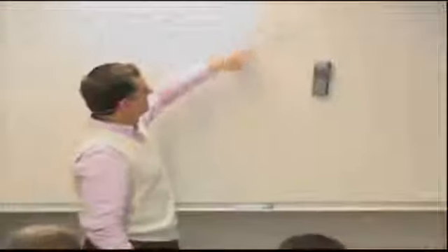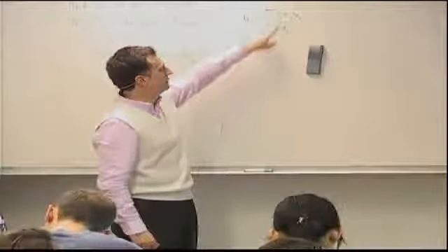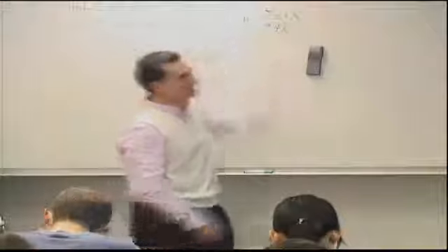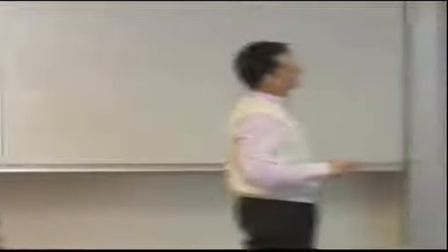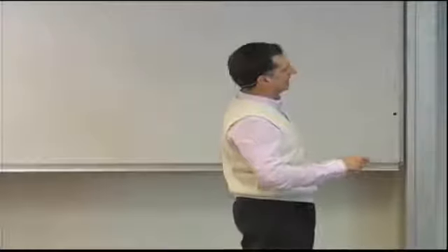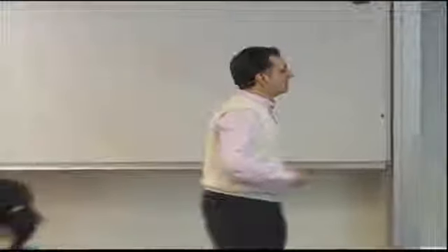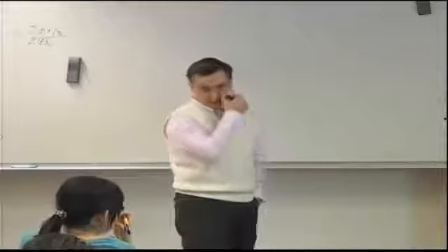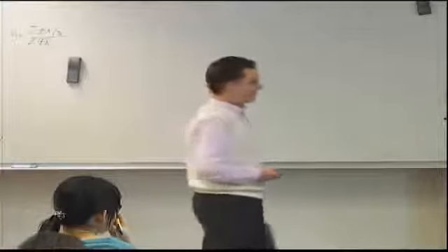Each member times its distance from the reference axis divided by the sum of all the EAs. And if all the members have exactly the same stiffness, what I was trying to say was that the E's will cancel, so I can resort back to my standard equation for Y bar. The reference axis about which I calculate the Y's is shown here. And this is a function of B2, which in our problem is a parameter. We have to vary B2 and find what's going on.